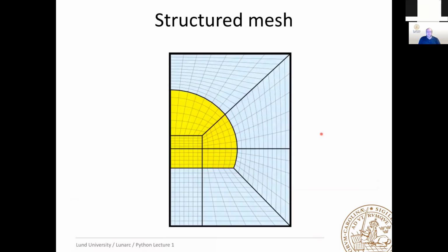But even if you have structured mesh generation, you can create quite complex meshes by using quad elements, super elements in this case. So here's an element with 1, 2, 3, and 4 sides. You can have curves on each side of these super elements, and then it generates the elements in the super domain or super element. Then you can combine them together to create this complex mesh. In this case, it's a tunnel here, and there is a symmetry line here.